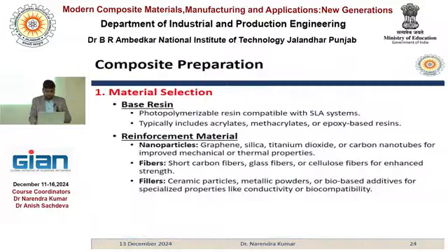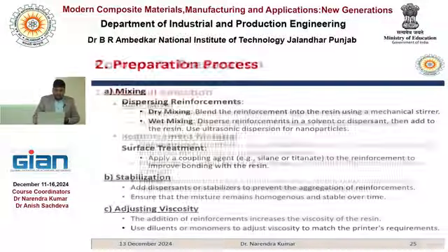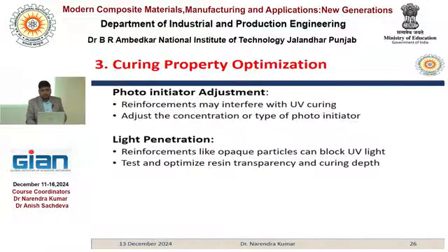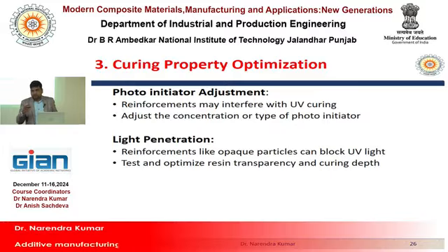you can take the resin first, then take the reinforcement material, then you need to do mixing, right? And then sometimes you need to add some photoinitiator adjustment because it may affect the curable feature of the material, right?